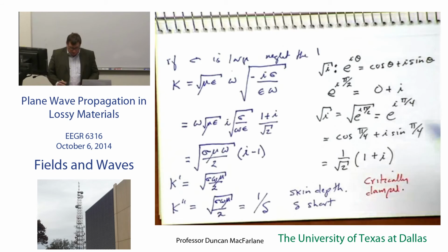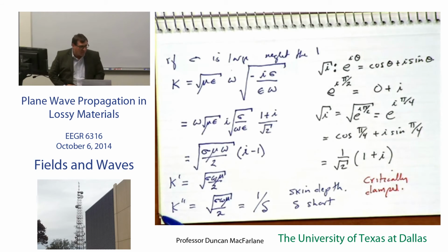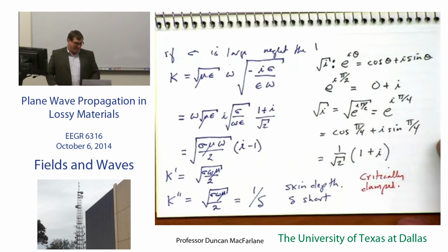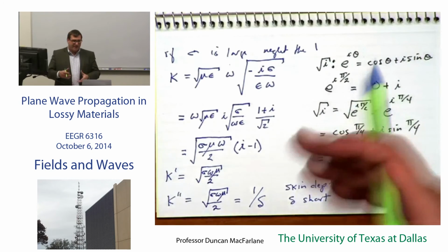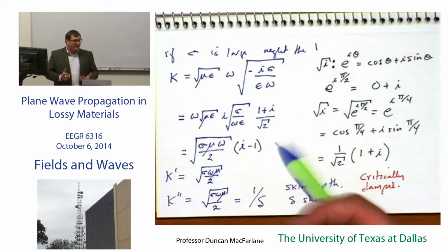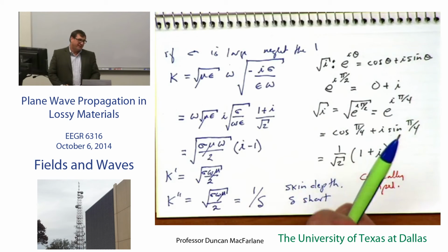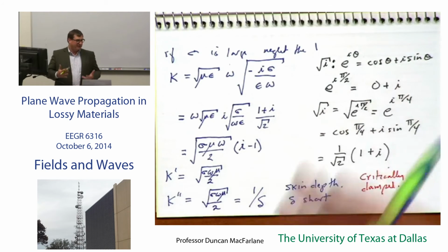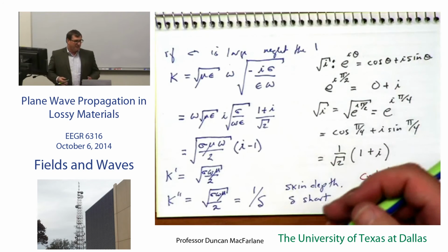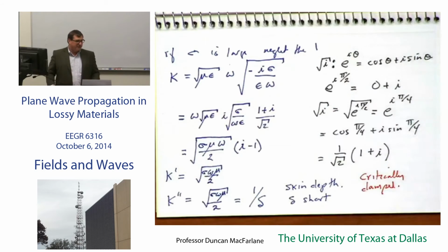So again, this is exactly the engineering part of it, right? What's your conductivity for gold or copper? Oh, by the way, what's your conductivity for evaporated gold and copper in your particular setup, right? Because if you evaporate it, it's not going to be quite as dense. It's going to have a slightly different conductivity. So you sort of have to either establish that or ballpark it or downgrade your, if you switch vendors, maybe you switch sigmas on those things.